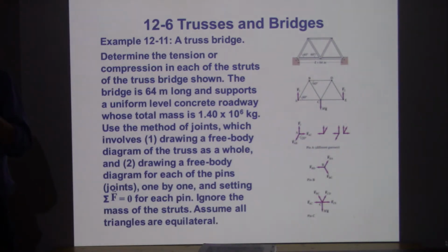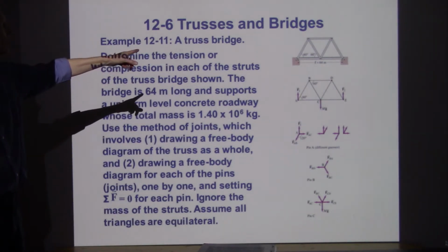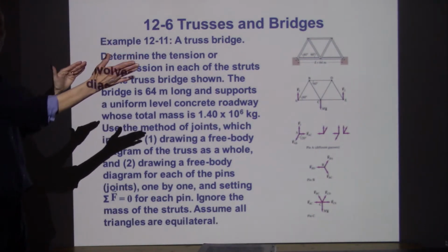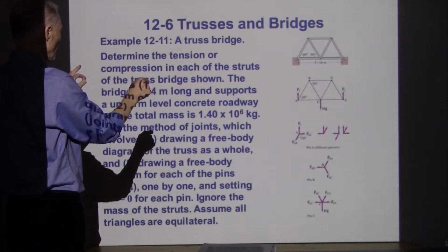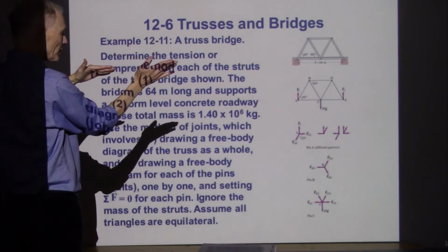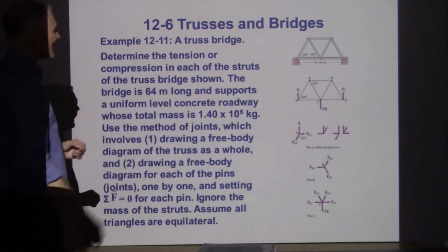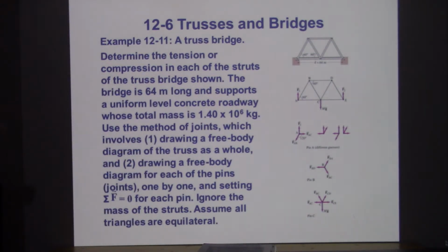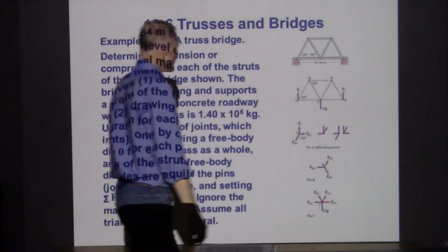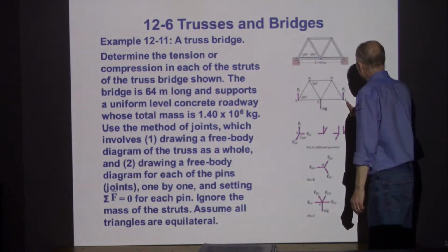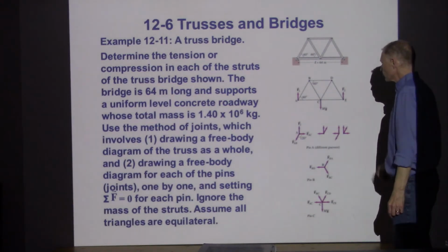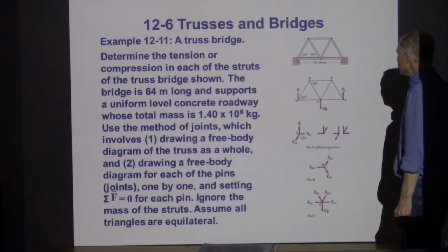A triangle won't shift. You can't change the lengths. If these were all done with squares, the square would just tip over, right? If I had a square set up with pins at the corners, the sides of the square can just tip over. That can't happen with triangles. So these trusses can be very, very sturdy. Now, they've labeled different points, A, B, C, D, E, and we're going to go into each of these and take a look at what forces are acting at those locations.